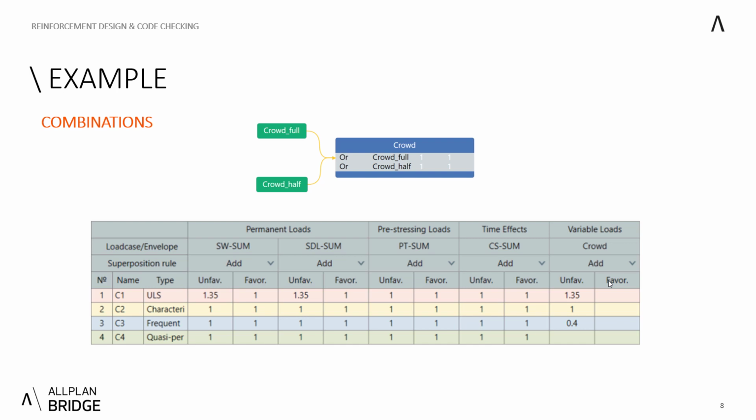Although in real life projects or in your country, you might end up using a combination group of 6.10a and 6.10b combination type. Also, as you can see, this combination table considers both gamma G factors and psi factors. Therefore, you can see that the crowd is being applied with both gamma G and psi factors for the respective loads.